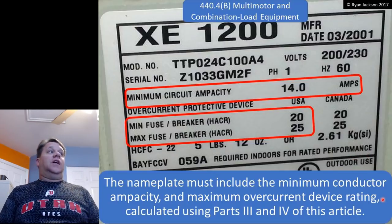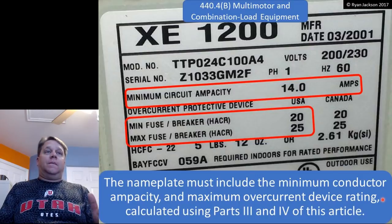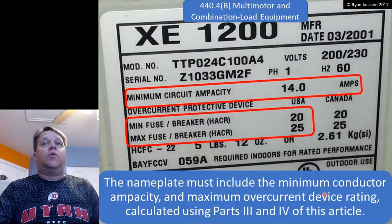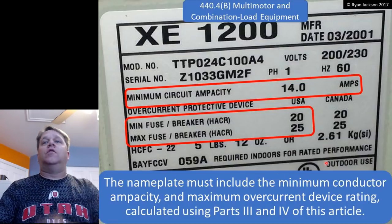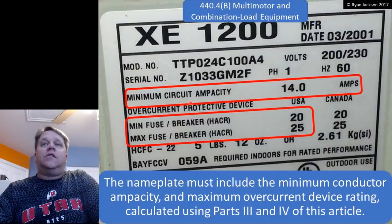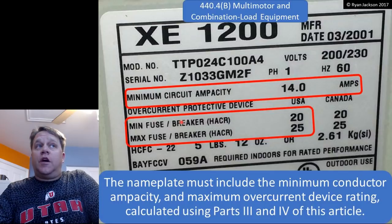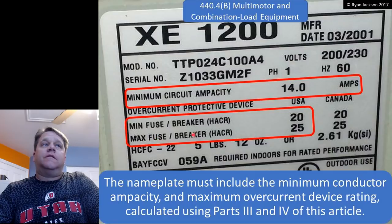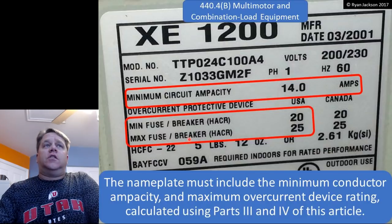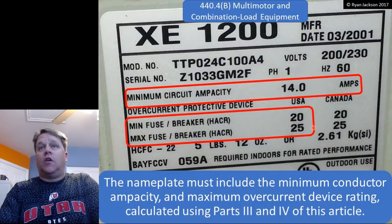Awesome. The code just said the manufacturer has to do all the math and they have to tell you what the answer is. It seriously says that in the code. 440.4(B) says the manufacturer has to do the math and they have to tell you the answers. And that's why it says on your nameplate minimum circuit ampacity, and sometimes it will tell you the minimum fuse or breaker, but it has to say the maximum fuse or breaker. And all you have to do, this is so much easier than you think, all you have to do is get a wire that satisfies the minimum circuit ampacity and a breaker or fuse that is not larger than the maximum breaker or fuse. That's it. That's all you have to do.